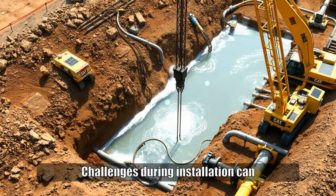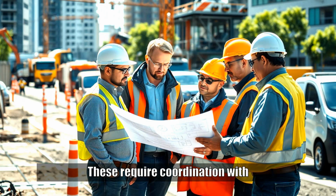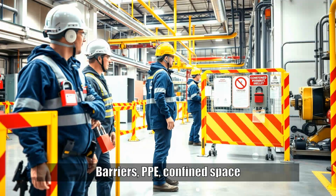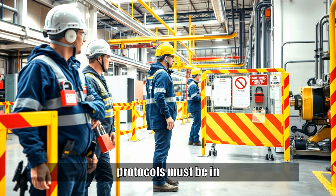Challenges during installation can include underground utility conflicts, rock excavation, water table issues, or dealing with existing infrastructure. These require coordination with civil engineers, utility providers, and often traffic or road authorities. Safety during construction is also paramount, as excavation and pressurized systems pose risks. Barriers, PPE, confined space permits, and lockout-tagout, LOTO, protocols must be in place.